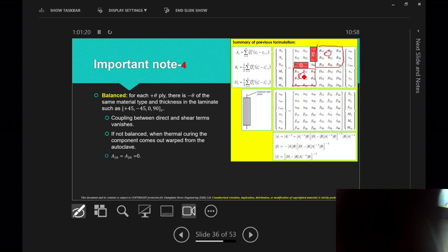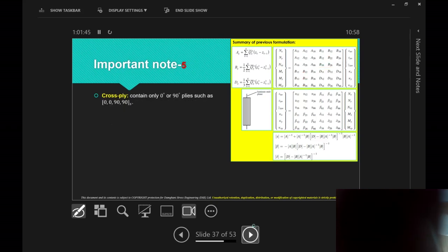That's most of the composites you'll be dealing with in industry: helicopter blades, wind turbine blades, wing skin, fuselage, and all of that. That's given, even for mechanical and automotive applications. But you can see already we've ignored the full potential of using composite with those coupling effects, which is not being used. So balanced, symmetric. We've got cross plies, which means just 0/90, 0/90, 0/90. There are no 45s, no angle plies, no 15, you name it. They're not good at all.